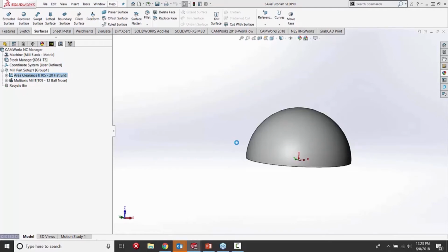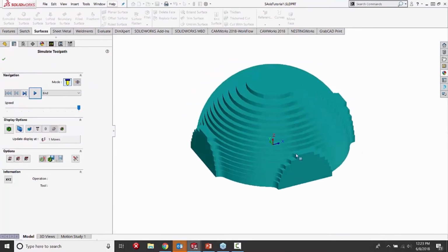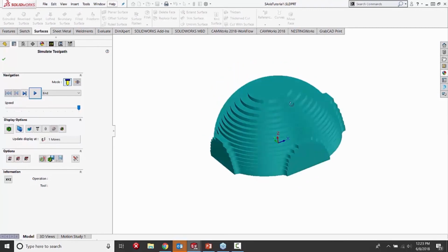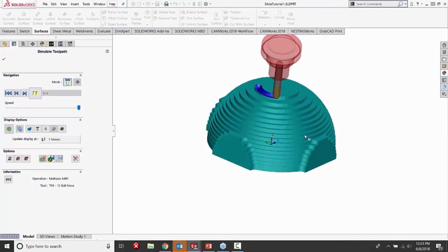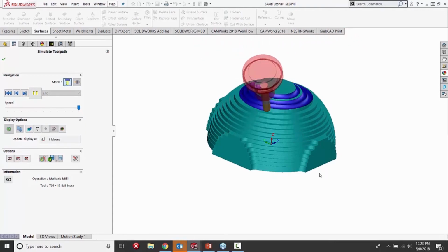we'll see the rough mill or the area clearance already performed on this object. Not to the best resolution, it kind of just cheats and goes as quick as it can, but it's a much better place to start to analyze this multi-axis mill. Just keeping the tool on surface. My step over amount's still a little too big, obviously, but that's an easy number just to type in and fix. But I'm really happy with this toolpath.